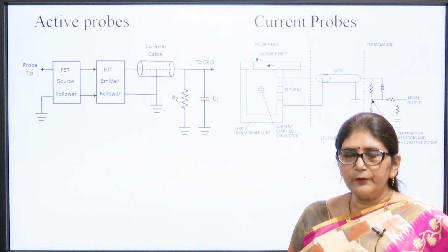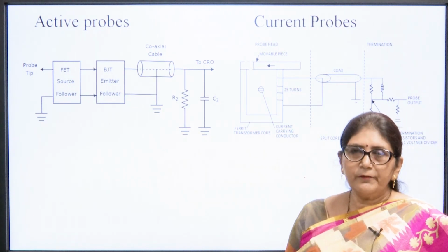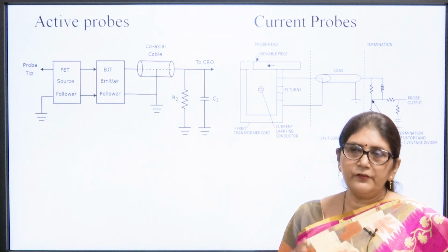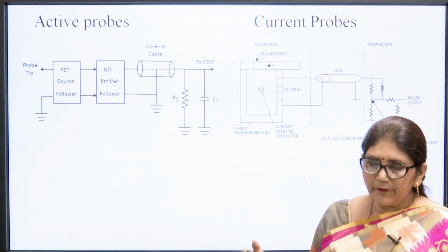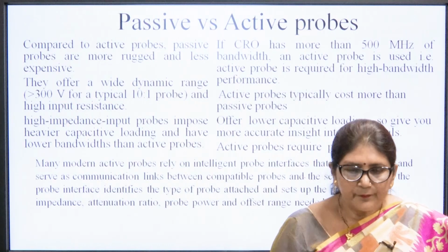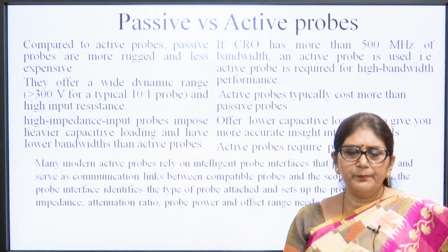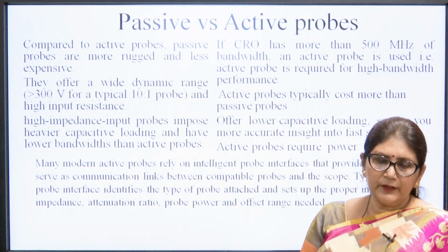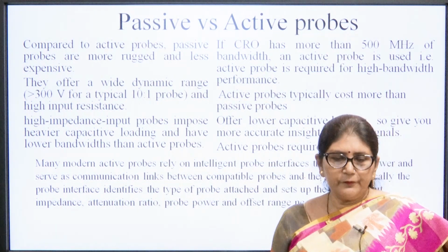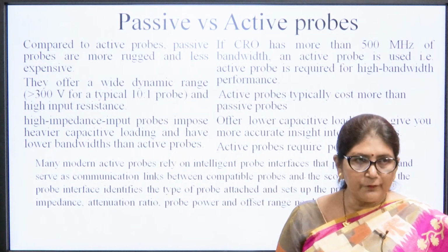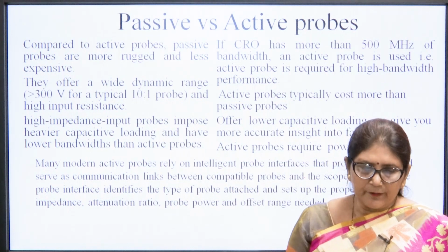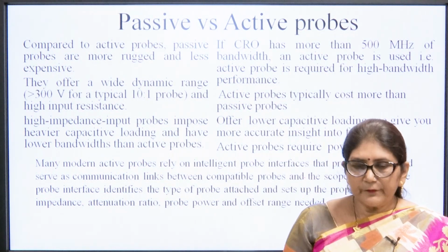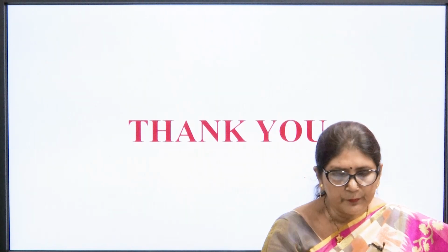In the high voltage probe again the capacitance problem is there. So, in the high voltage probe shielding is provided and we can measure a 1:1000 ratio of that signal. So, these are the differences between passive and active probes. We know the passive probe can be used for less than 300 volt, and the active probe we can measure up to 500 volt. So, these are the basic differences between active and passive probes.